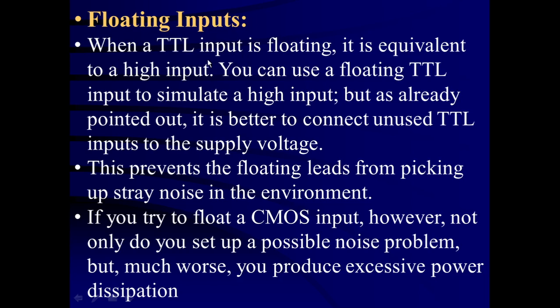When a TTL input is floating, it is equivalent to a high input. You can use the floating TTL input to simulate a high input. But as already pointed out, it is better to connect unused TTL inputs to a supply voltage. This prevents the floating leads from picking up stray noise, RF signals, from the environment.